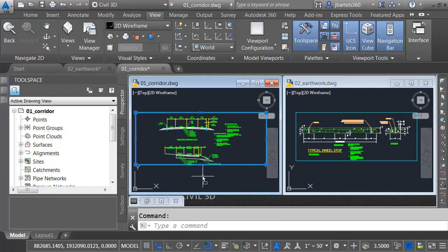I will then select the polyline. I'll hover over this grip in the middle and I'll choose stretch. Maybe I'll tap my F8 key to lock my ortho, and I'll drag this out to make it a little larger. I'll press escape when finished. Not only can we drag and drop content between drawings, we can also match properties between drawings.